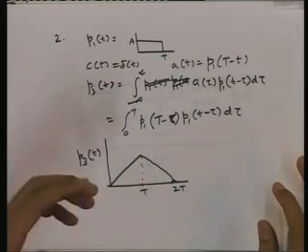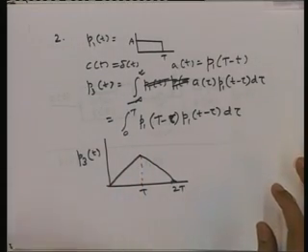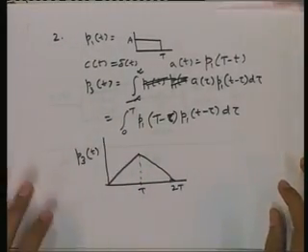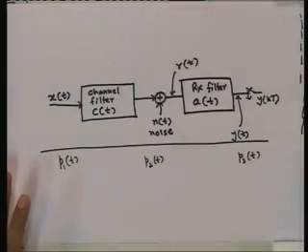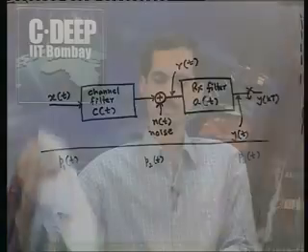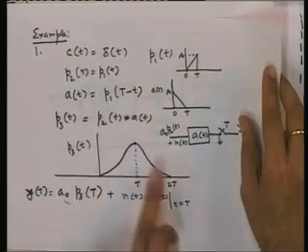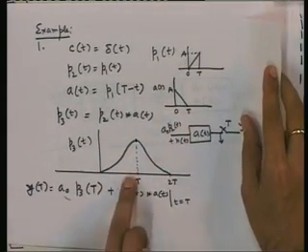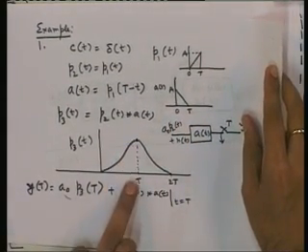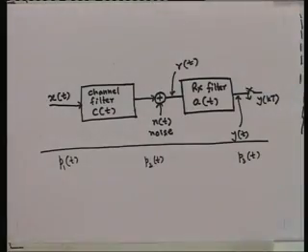The noise is the same and the signal is scaled maximum, so it gives us maximum SNR. Similarly, for the triangular pulse, p3(t) is again maximum at capital T. So sampling every capital T seconds is the most beneficial in terms of SNR.